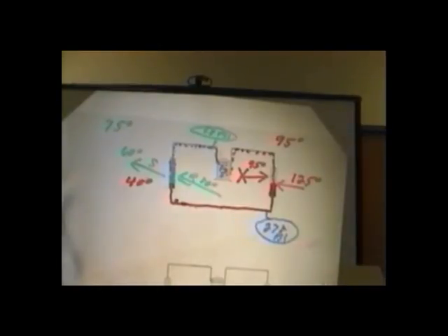Now, let's continue. Now let's take a thermometer, and let's stop here, and Jeff, we're going to show them the electronic thermometer again, because this is where you use this kind of an instrument in refrigeration. We're going to tell you to take a thermocouple. Now keep in mind, this is only one method of taking temperatures. Boy, I guess today they got all kinds of instruments. They've got little clamp-on accessories for digital thermometers that you can just clamp on these lines, and they are really terrific. I guess some technicians even use infrared, but I understand you have to go very close with it. Whatever method you have, as long as it's accurate, it's got to be accurate.